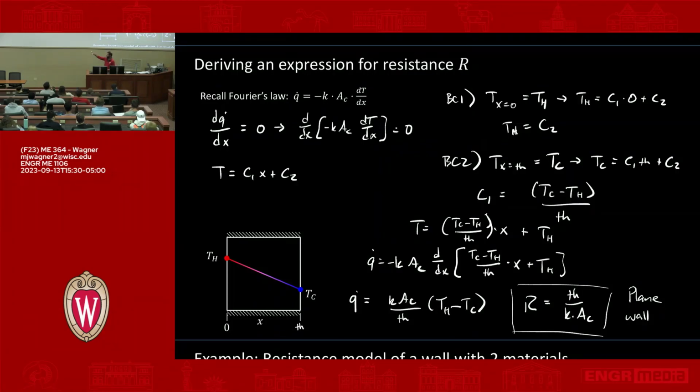This is the exact solution, so it works for this problem. If we start getting more complicated situations, or the boundary conditions are different, then it no longer applies. This is only for the known temperature boundary conditions in a plane wall situation.